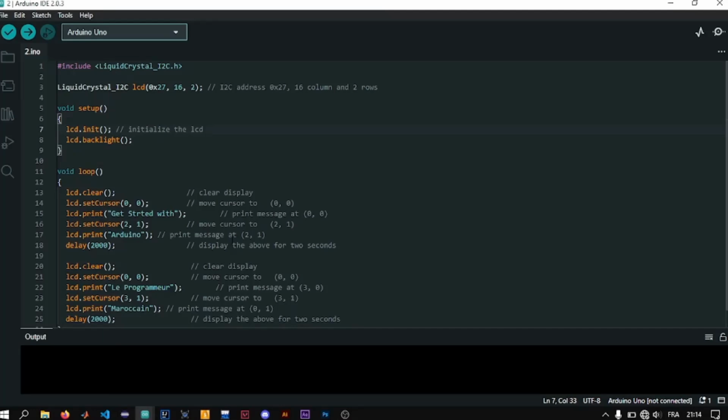For the second code, we are using an LCD, and if you are lucky to have an LCD with built-in I2C, you're not gonna need many wires. I2C is a bus protocol, and it allows the LCD to communicate with the microcontroller using only two wires, named SDA and SCL, instead of the 16 standard wires. I2C is a serial communication, and it's a great thing to learn. There are many serial communication protocols out there, each one with a use case and its properties.